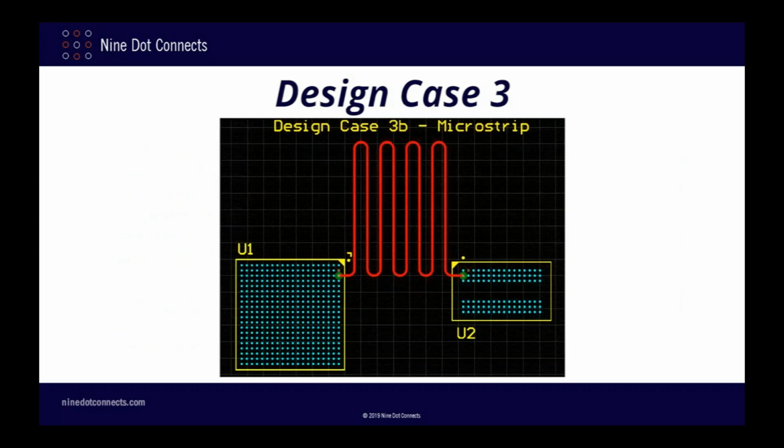And in one last concession to improve clarity, I've put the components on the bottom of the PCB and used vias to connect to both the strip line and the microstrip. Even though I could have routed the microstrip on the same layer as the components, I did it this way so that both the designs use vias, thus giving me as much commonality between the different design cases as possible. It also matches the geometric diagrams I've been using with the microstrip on the top layer.